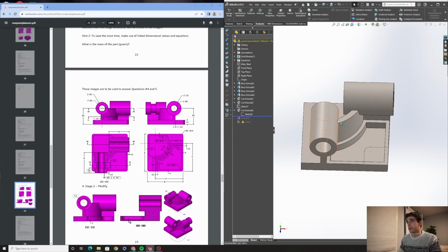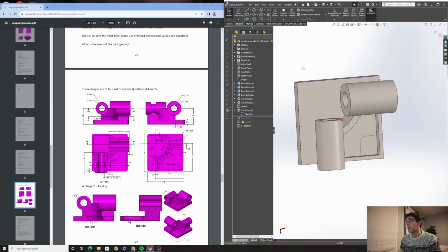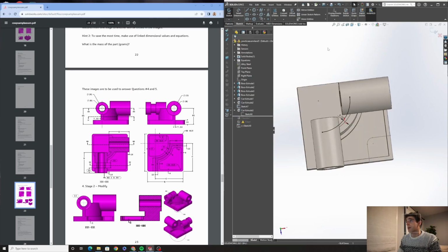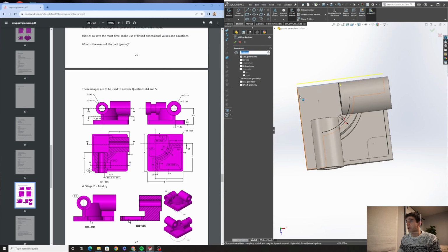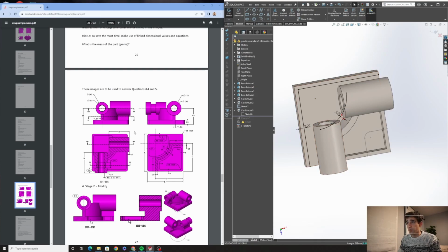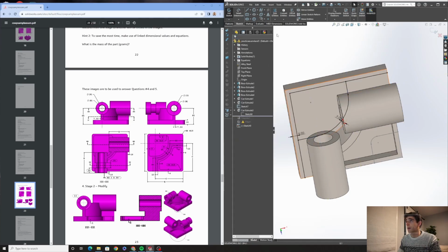Let's roll back up here so we can do some more edits. Then over here, it looks like we have an offset from this circle, offset from the edge. So let's sketch on this again. Offset entities, this here, reverse. Entities, and we'll grab these two edges, reverse them in. So you'll see this doesn't connect as smoothly, but it looks like I have a tangent line from the circle over. So I can use my mouse gestures, just create a tangent line over here,